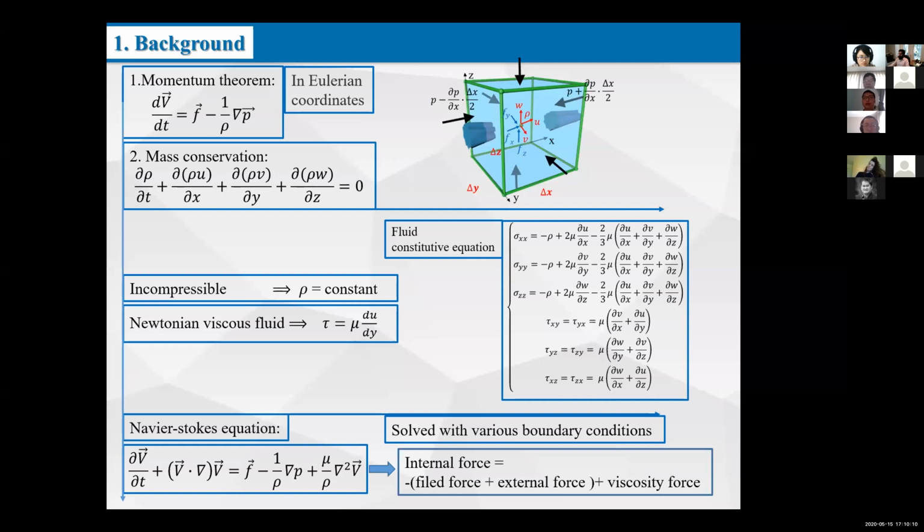As about the cubic law, there are some basis should be talked about. Because the cubic law is always the ideal situation. However, a cracked concrete, such as the cracks, it is not the ideal. It does not follow the ideal situation. The cubic law is the simplest situation with parallel and smooth plate model. It is the simplest situation from the Navier-Stokes equation.